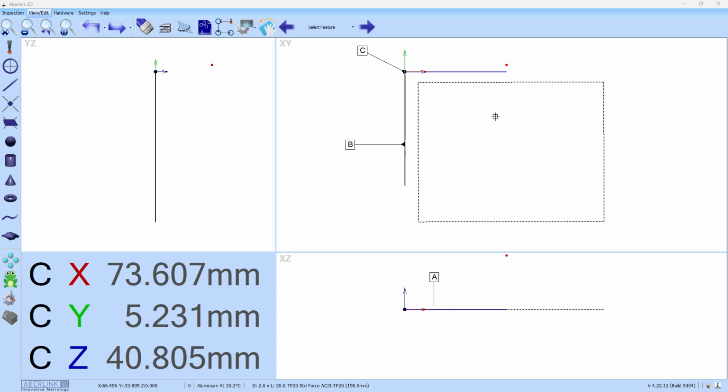So we've measured the reference system. So again, to follow the example, it's the datum A plane on the top, the datum B line, so that's side left hand face. We've then measured the back face as a line and constructed a point where the corner meets, and that corner is the datum C reference origin. So what we need to do now is firstly measure the larger bore that we want to zero out the positions for. We can then apply this as a datum and then apply that datum to the features so that the features are located via the datum frame versus the reference system as they would as standard.